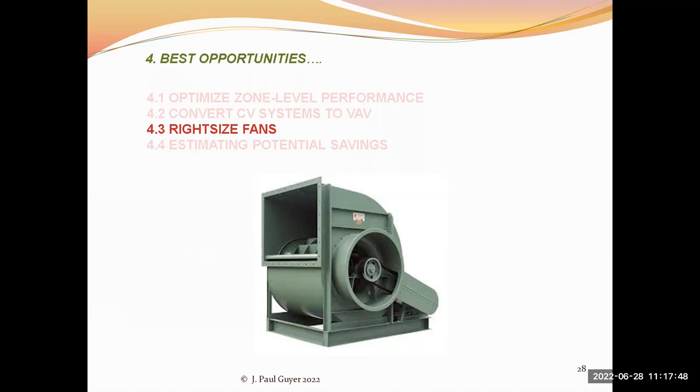So, diagnosing oversized fans: the potential may exist, and building maintenance staff are the first responders, so to speak. And the first method of diagnosing the oversized fans is to measure the static pressure of the main supply fan.